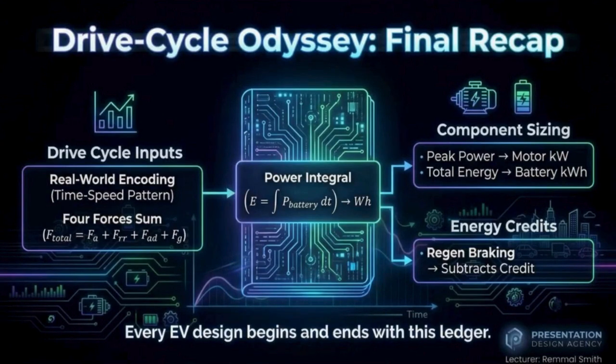Four forces act on the vehicle: acceleration force, rolling resistance, aerodynamic drag, and grade force. Total force equals the sum of all these forces. F total equals m a plus F rolling plus F drag plus F grade. Power is calculated from force and speed. P equals F total times V. Energy in watt-hours comes from integrating power over time. E equals integral of P with respect to time.